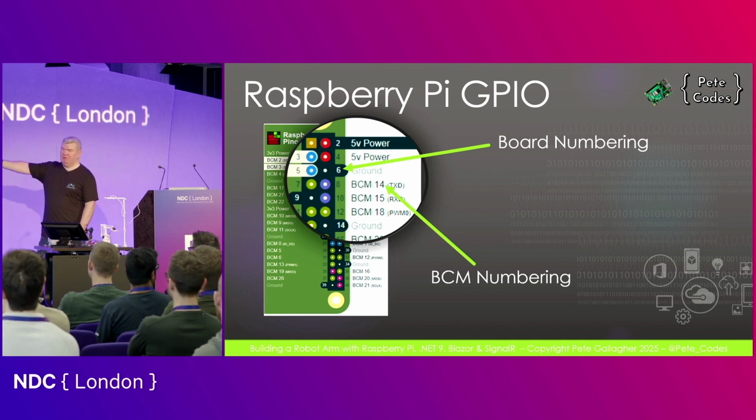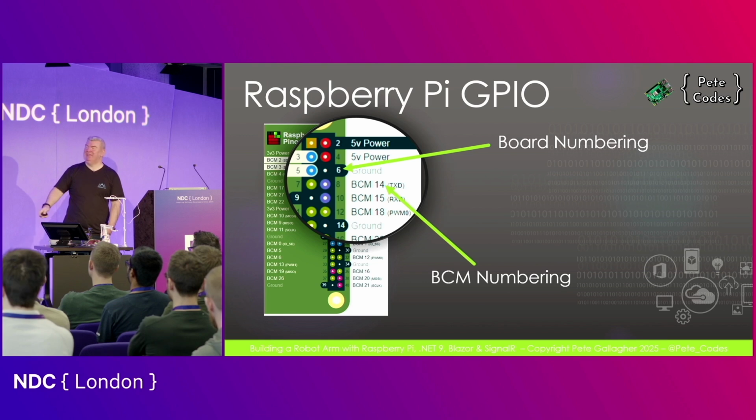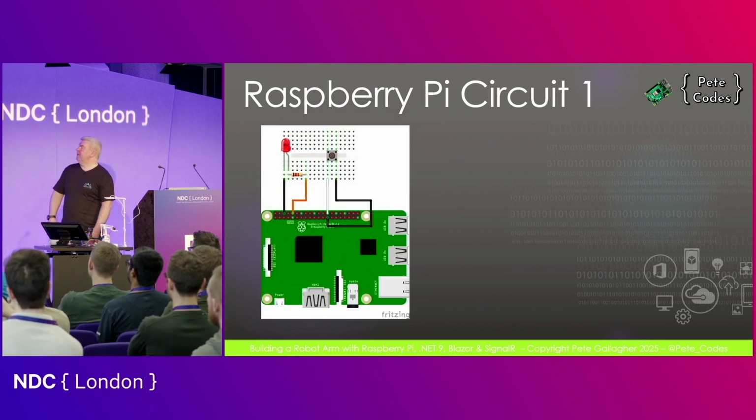For the love of God, don't just do the BCM, don't do it. I don't know why people do. I can count those pins, so just use board numbering. But you'll see that in the code in a bit.